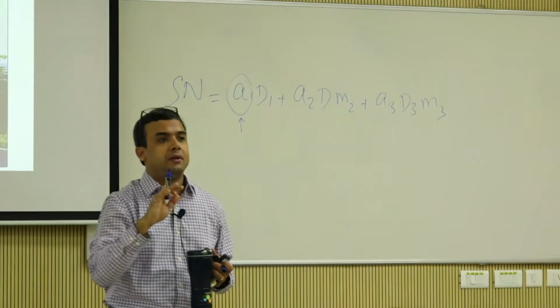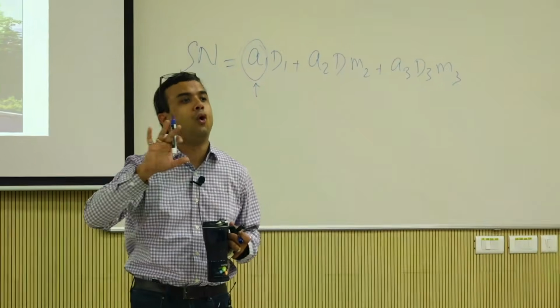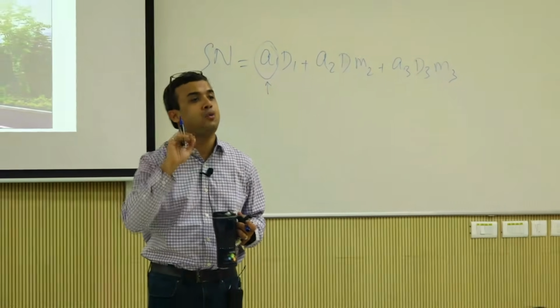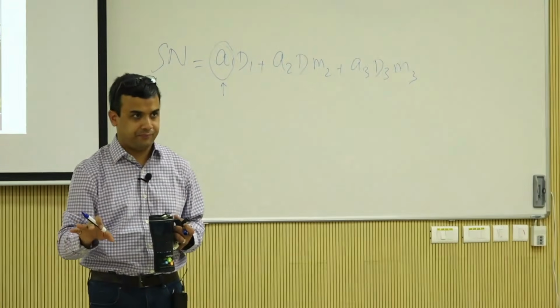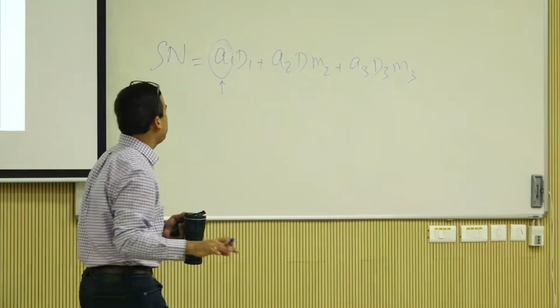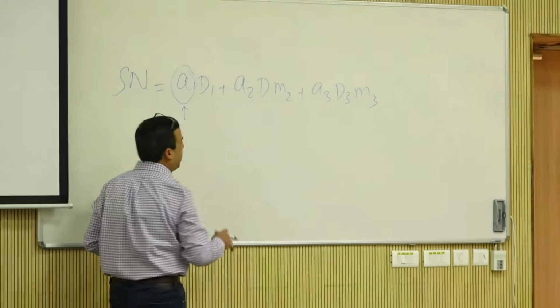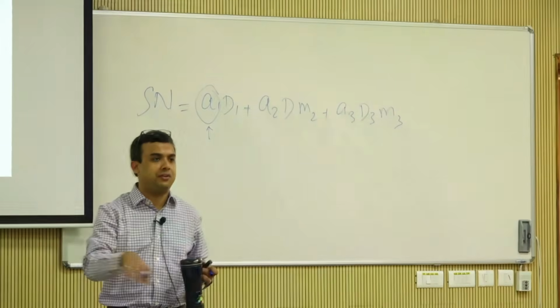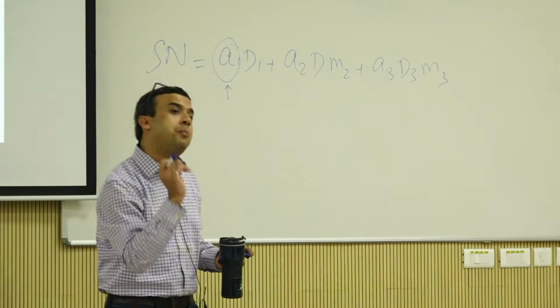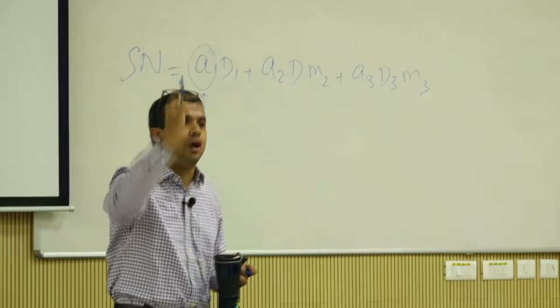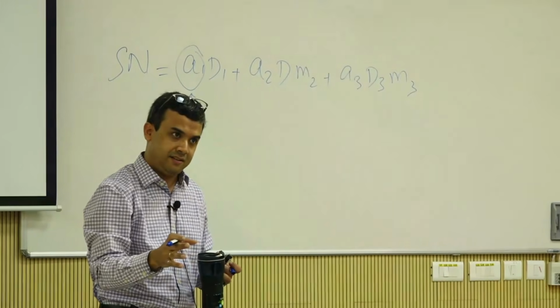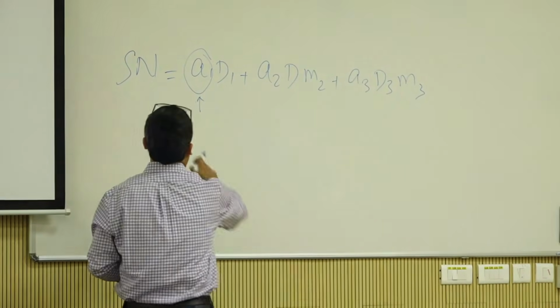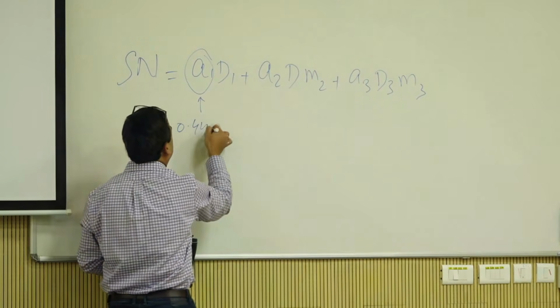So let's step back. Remember what I said, the old pavement design methods were all about protecting the weakest layer. So in AASHTO, you're basically plugging in the resilient modulus of the layer and saying how much pavement I need to protect it. And that A1 is for asphalt, it is 0.44, something like that.